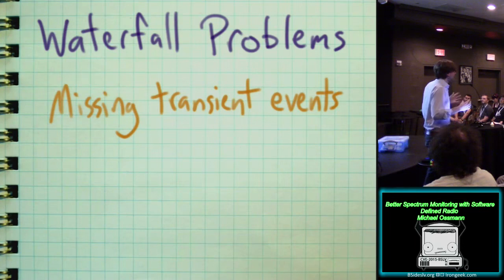And that's just one example. Our daily lives are full of more and more interesting digital wireless technologies that use super, super short packets of information. And you can completely fail to observe them even if they're right in the middle of what should be in your waterfall display, because you didn't happen to get lucky enough for one of them to happen at the right time, so you get a little tiny blip in one horizontal row of your waterfall. Wow. So transient events are very difficult to observe with this type of display.